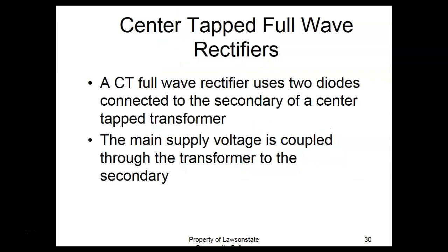So a center tap transformer, this is the first one we looked at. We have a 12.6 volt center tap transformer, and like I say, the actual trainer doesn't label this like it is. So 12.6 volts center tap, which means we would get 12.6 volts all across here, and we get 6.3 volts between here and here, and this is RMS. So on AC, if we don't specify RMS, then it's assumed to be RMS.